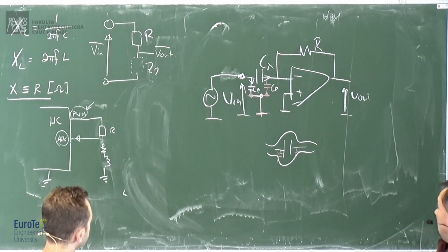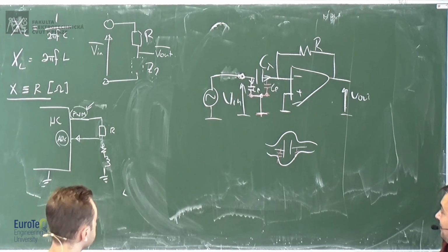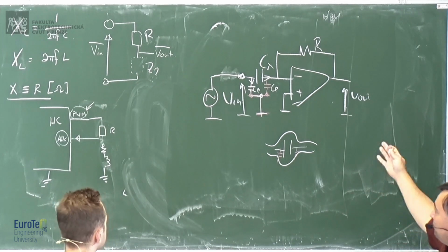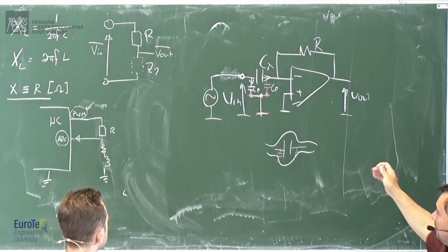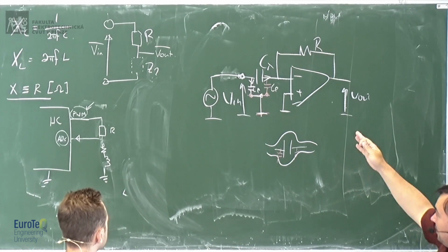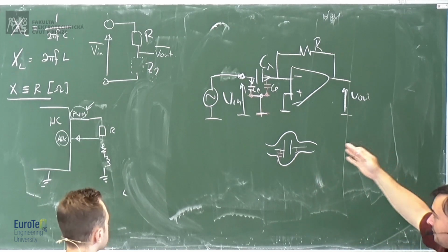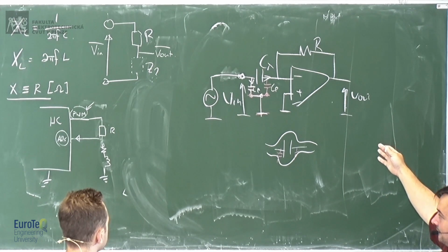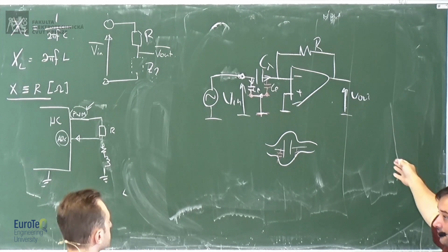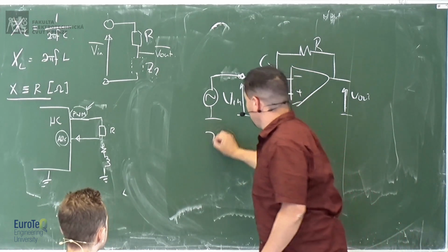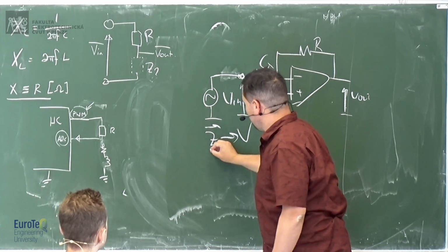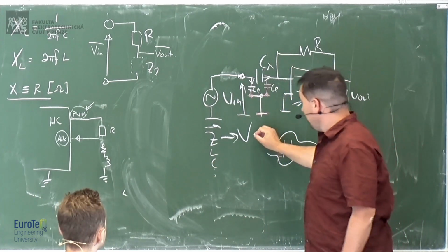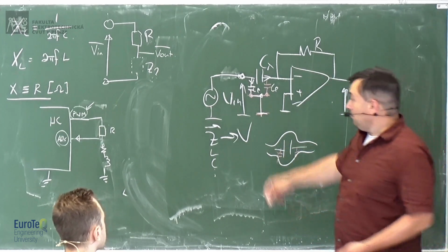So this is good because if you want to measure an impedance that is continuously changing, you have to transform it into a voltage, because then you know how to measure voltage continuously, okay? So you need to transform an impedance, reactance, or a capacitance, or inductance to a voltage. Okay, so you have to convert some value to voltage. Yes. This could be inductance, capacitance, whatsoever, or a combination of them and so on. And then you measure the voltage. Fine. But of course, there are all these sources of uncertainty.